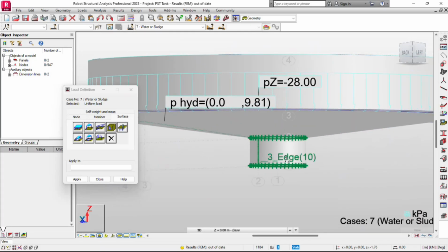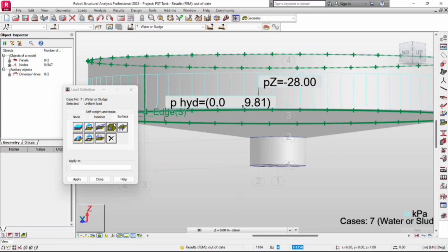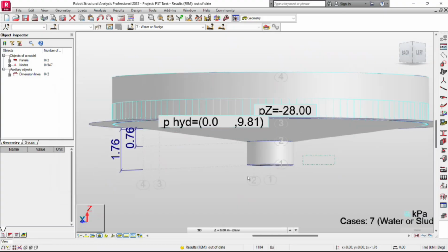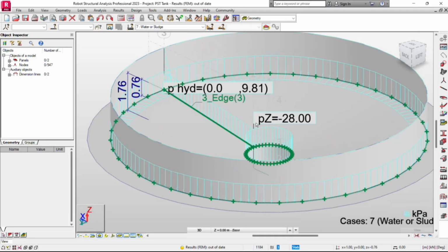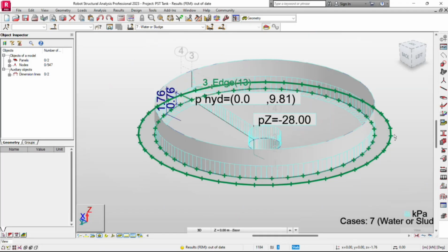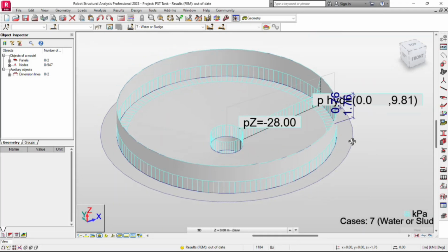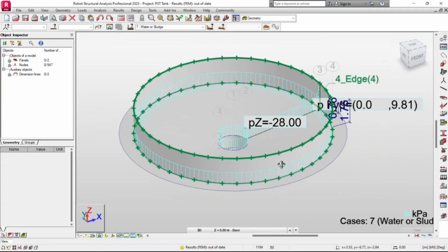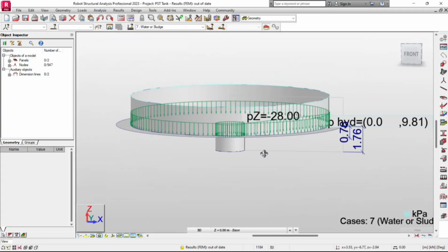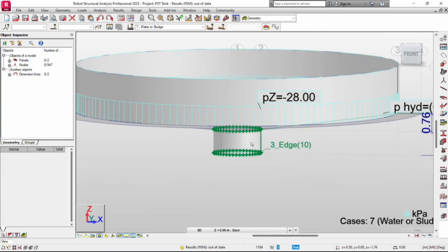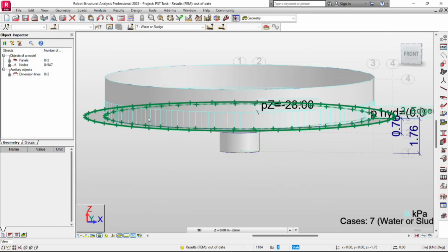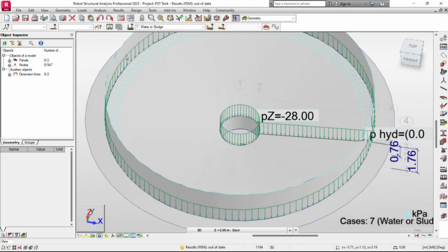And now our last, we will be focusing on the last application of loads. We will be focusing on this upper area. So I'll just select this upper area. We can select it because it's, again, a polyline. I have a suggestion. When you do the polyline to create the geometry, make sure that you do the polyline one by one so that this element will be separated from this element, and from the wall element.